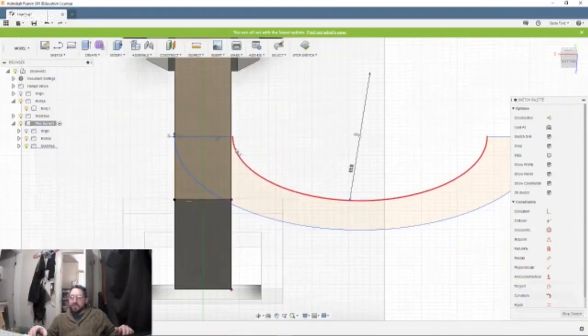You've lost all orientation to that 35 millimeter thing of the circle. If you were to edit that now, it probably would just go wonky on you without having a reference point. I mean, you can extrude it, but if you went to edit that and make it say 37 millimeters, it might freak out on you without a reference. It's like this little blip right here. That's going to be an issue, but I'll just smooth it out with something.